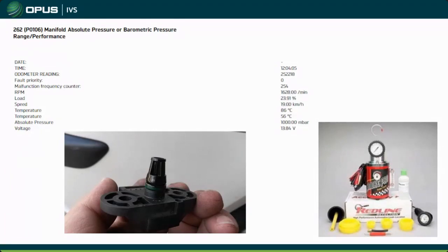That's with the 2-liter, the 3-liter, because they've made so many changes. Really, your best bet is to get a factory one and make sure that it either matches the exact part number of the one that you're taking off, or if there is a supersession, that you check your software and that it's going to be compatible. Because I have seen a lot of cars where they correctly diagnose that you got a bad breather valve, but they put the updated one on, and they've never done the software update, and then that's where we kind of run into an issue. So let's just be aware of that.